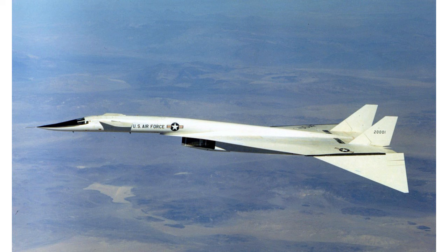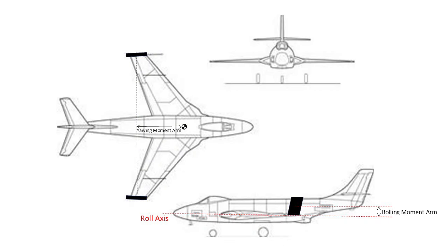For efficiency, the winglet orientation doesn't matter too much, but it does for maneuvering and handling. Think about the upturned winglet during a turn involving a roll. As the left wing rolls right, the left wing will generate more lift, and the winglet inherits some of the wing's increased lift. I won't go into too much detail about that, I'll leave that one for homework. This means that the left winglet's inward pointing force increases, and since winglets are usually on wings with some sweep and aft of the CG, this inward side force will now yaw the aircraft left away from the roll, which is normally what we refer to as adverse yaw.